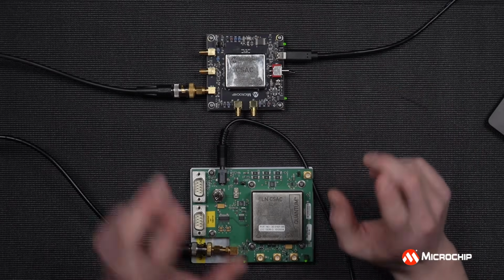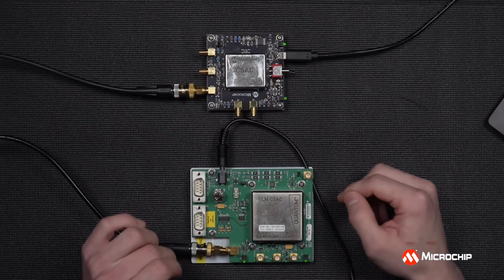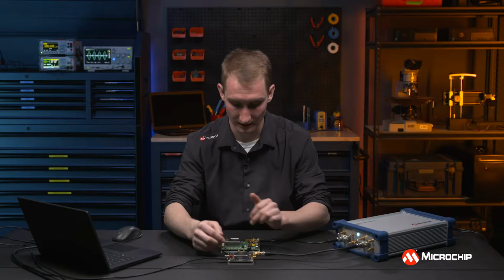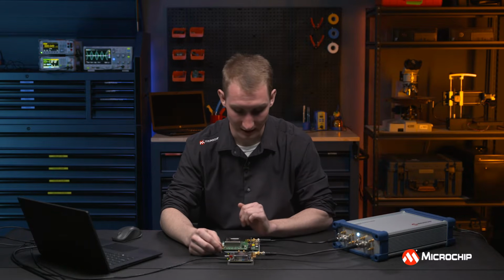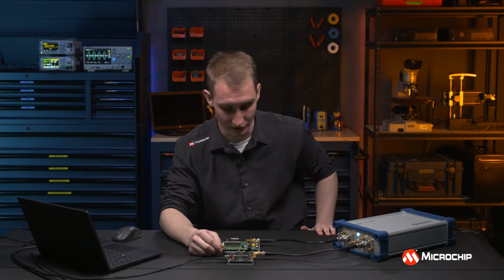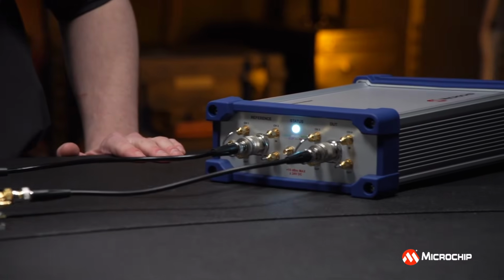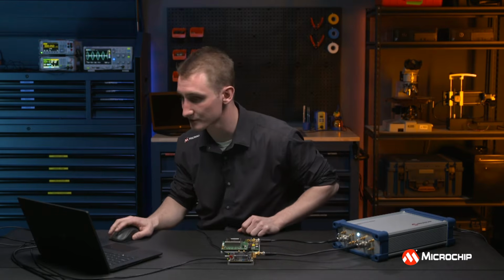My name's Chris Higgins, and today, we're going to be setting up some automated test environment scripts using the 53100A phase noise test set. So what I have in my setup today are two atomic clocks. We have our low noise chip scale atomic clock and our regular chip scale atomic clock, and our test set, the 53100A phase noise analyzer. Now, let's say we're going through production. Let's say these aren't atomic clocks, but say whatever oscillators you're manufacturing. Let's look at a couple different ways to make test scripts to make the measurement process a little bit faster.